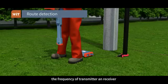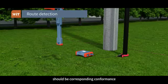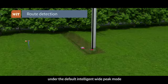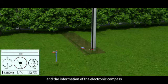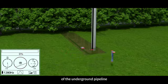After power on, the frequency of the transmitter and receiver should correspond. Hold the receiver to find a stable signal under the default intelligent wide peak mode. The signal amplitude and the information of the electronic compass can intuitively display the accurate location of the underground pipeline.